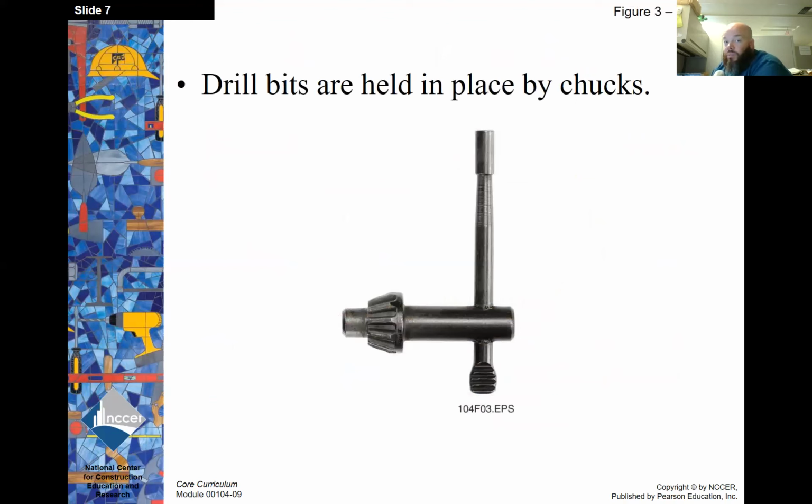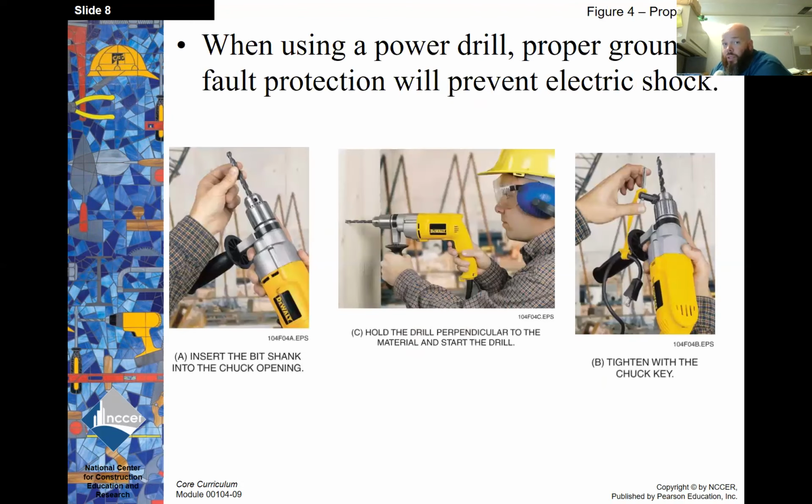Drill bits are held in place by chucks, and this photo actually shows a chuck key. Always remember when changing out a drill bit, to always remove the chuck key before starting the drill motor. When using a power drill, proper ground fault protection will prevent electric shock. So here's just a little diagram of operating a drill and replacing the bit.